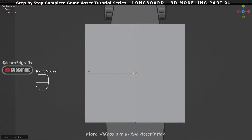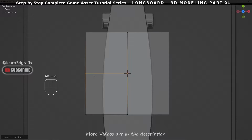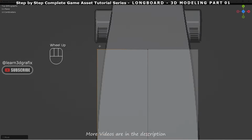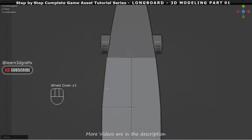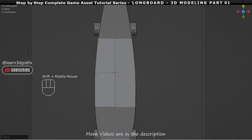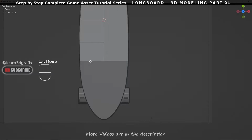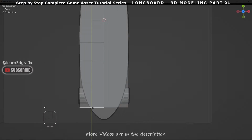Press Ctrl R to insert an edge. Go to X-ray view by pressing Alt Z. Now select these vertices and match with the reference image. Press 2 and select the middle edge. Press Ctrl B and scroll the wheel to insert 3 edges. Select this edge, press E and Y and drag it to the bottom.